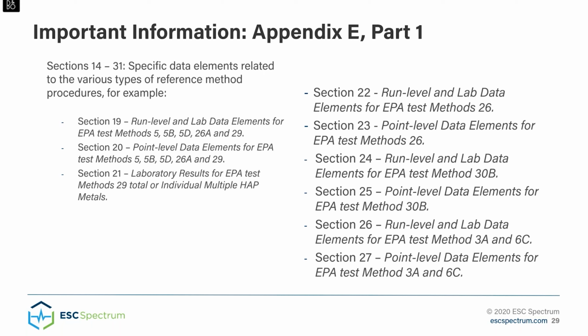This is where I mentioned before that if you can get a CSV file from your stack tester, you can hopefully import this data into StackVision or Prism and save yourself the trouble of hand entry. I'm going to assume that we're going to have the ability to hand enter all this information, but you can see that it's a lot of detailed information, and if you had to hand enter it, it would take you quite a while. I would like to encourage you not to rely upon hand entry. If you can get a file from your vendor, from your stack testers, I should say, importing the data into the database would be a much easier and much simpler way of doing it.